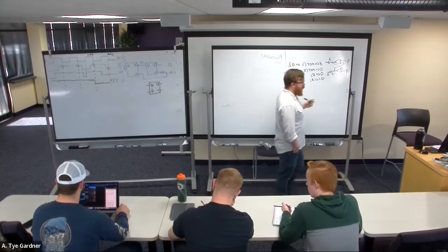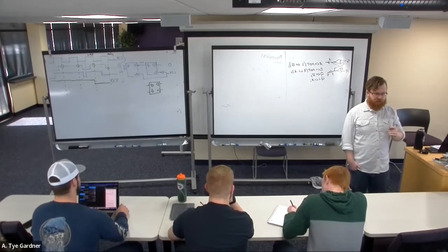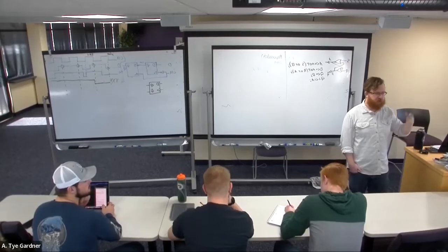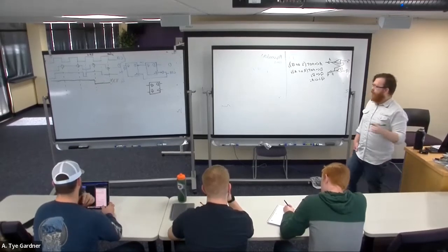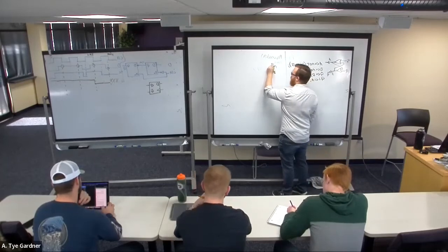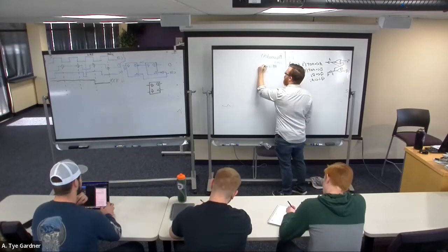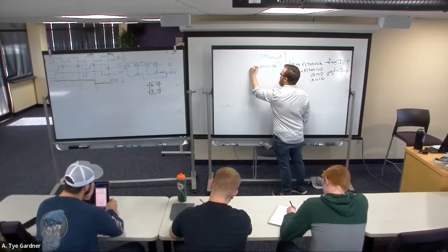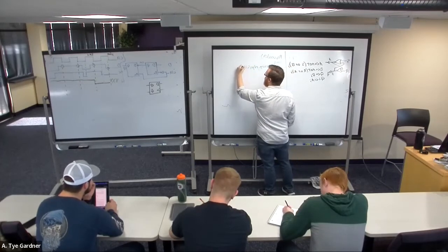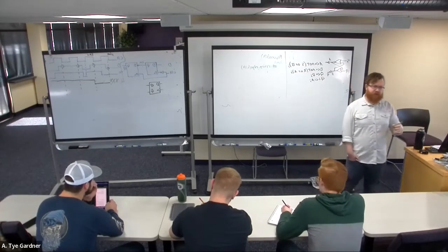Then, in order to react to only the rising edge of the clock, because right now it's going to run the process if the clock goes from 0 to 1 or 1 to 0, they gave us this nice little bit of code that says, if rising_edge(clock).